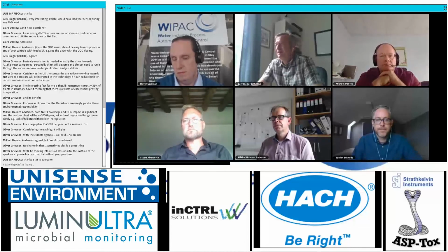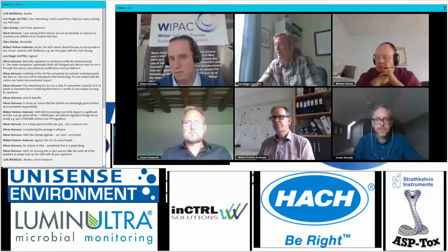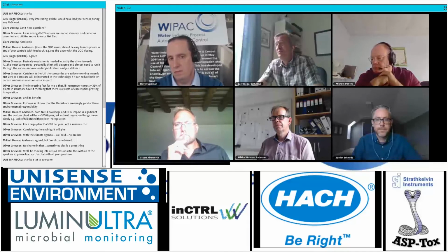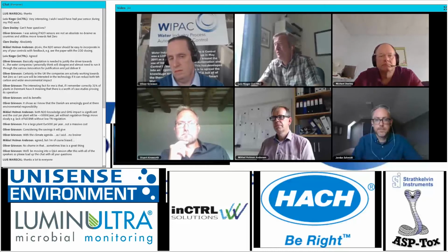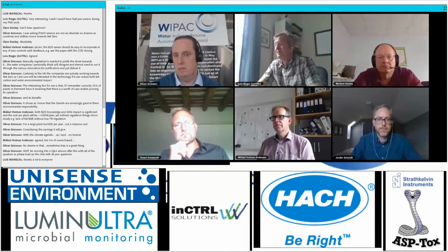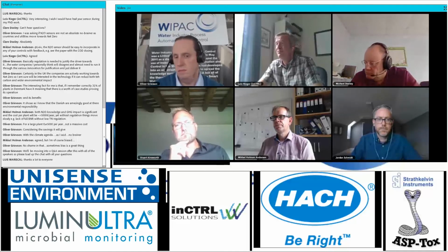Another one not really discussed is the cost of operating these systems. My rule of thumb is 1 to 2 hours per sensor per week. And that's a realistic number we actually monitor, how much time goes into that. And there's always that odd moment, and it's not the fault of the suppliers, but it takes time. And if you include that in the cost-benefit analysis, unfortunately for smaller plants, there is no benefit.